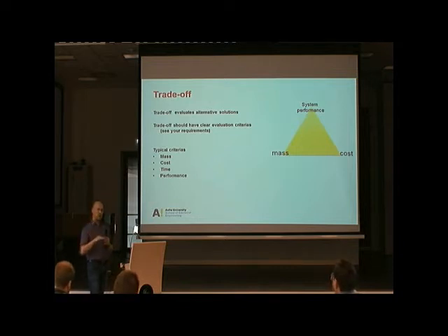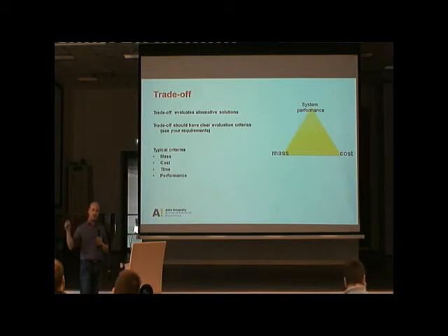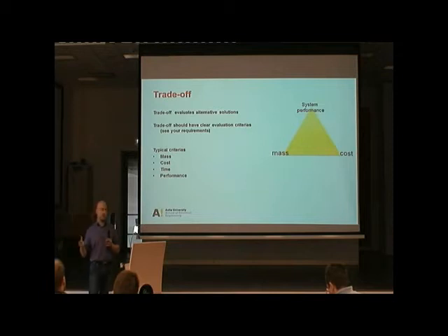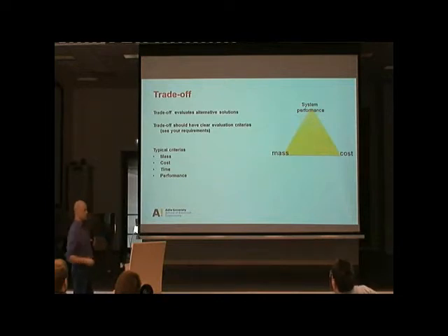first decide what are the good and bad points and what is the most important thing for you. And then you just list different solutions and give them points or marks. And after filling up the table, the right solution will stick out, hopefully. Or there might actually be a couple of good solutions even. But this is the most useful tool for a space engineer when you need to make decisions. You make a trade-off between two decisions, and it's better to make this trade-off with documented matrices so that you keep these decisions for later use.